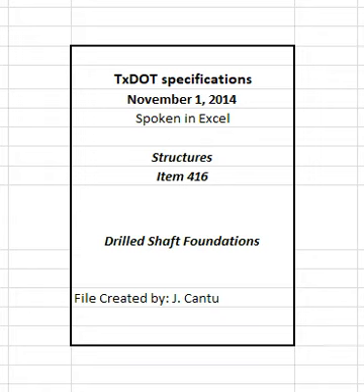or under slurry. Use concrete with slump that meets the requirements of Table 2 as determined by TEX 415A. Table 2. Slump requirements. See table in specifications. Perform a slump loss test in accordance with TEX 430A before beginning work when casing is to be pulled or concrete is to be placed underwater or under slurry. Provide concrete that will maintain a slump of at least 4 inches throughout the entire anticipated time of concrete placement.